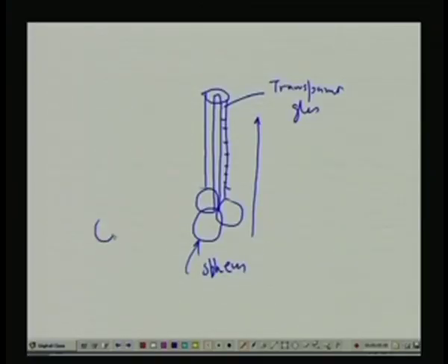So, they actually use three, if you take a top view, three spheres made of plastic, 120 degrees apart. If I take a side view, it will be like this, three spheres on one float. So, if the flow increases, this will go up. This is calibrated in terms of that.